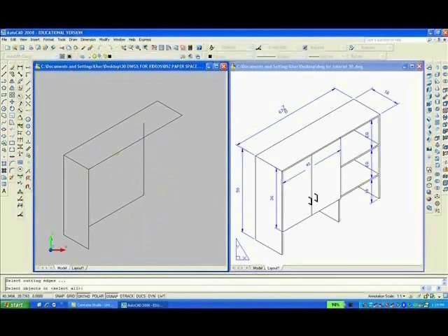I'm going to trim that portion of the line off. Then we're going to draw another line from the midpoint of this one. No, escape. Line, midpoint. Here. That'll go up. That'll give us the doors. Enter. Then I'm going to trim. TR, enter, from that line here.